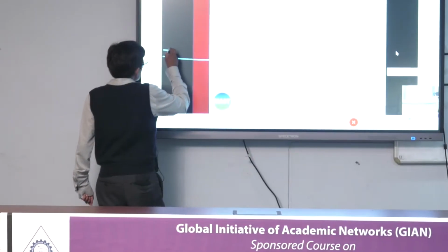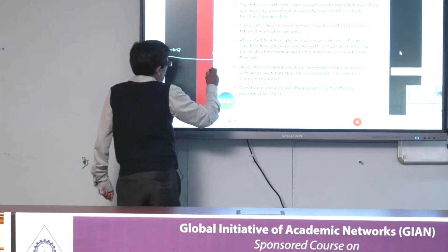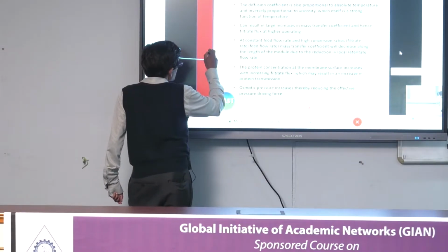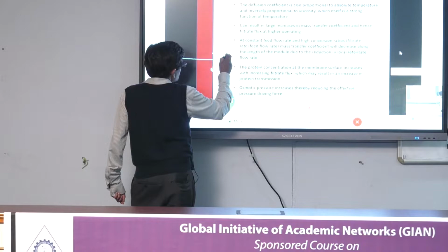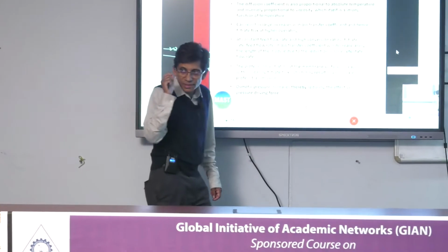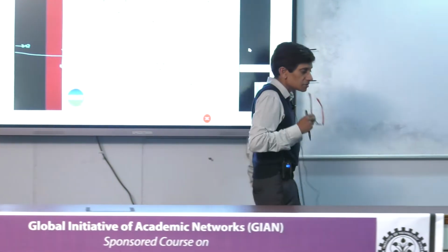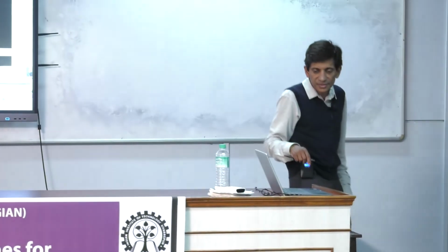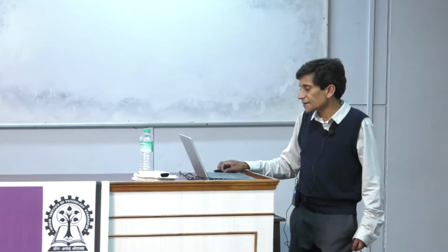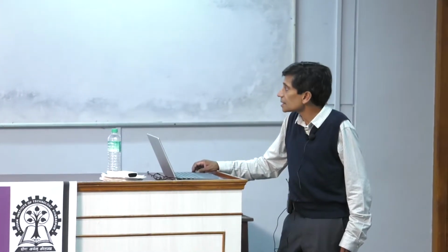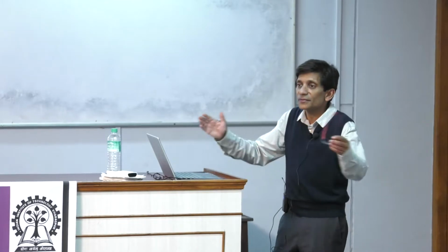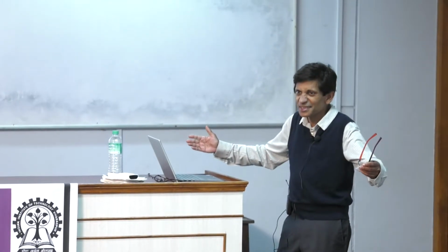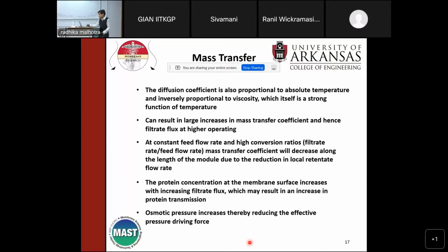So your feed is coming along here, and a large amount of it is decreasing as permeate, then Q here is going to be much less, right? So you have much less feed. And so the velocity changes and so forth, and so all this is telling you is that if you have these conditions, then there's going to be a change in the mass transfer coefficient. I also mentioned earlier that if you have longer modules, right, the overall flux is lower for the same reason.